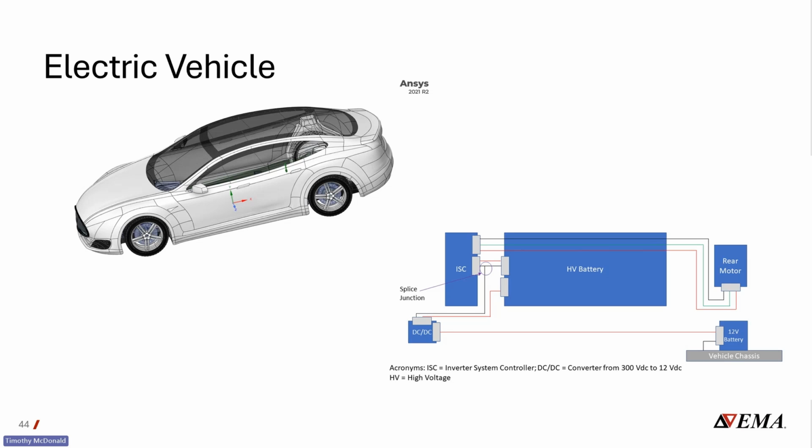The same radiated emissions comments that I talked about before apply, where we want to be judicious about the excitations we apply and make sure that they're realistic and that we're picking ones that are at risk to be close to the emission limits. There's no technical limit on the number of excitations, but it's an engineering time-saving limit to limit those to the worst case.